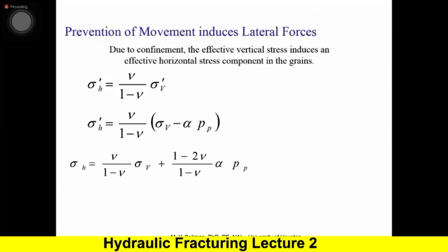Basically, when we calculate Poisson's ratio, we're saying it's unconfined, and we calculate how much lateral strain you have. But if that rock, where you're applying stress, is part of a huge formation, then it doesn't have room to expand. Then it's applying stress. So Poisson's ratio also is saying when I apply stress vertically, part of it is going to transfer horizontally.